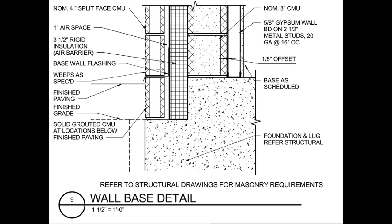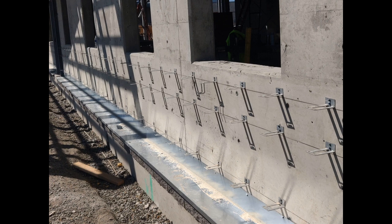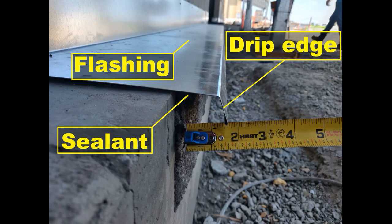Through-wall flashing and weeps. Provide reinforced membrane sheet flashing, metal or coated metal flashing. Install through-wall flashing at obstructions in the cavity and where indicated on drawings. Ensure continuity of the flashing at laps and inside and outside corners by splicing in a manner approved by the flashing manufacturer. Ensure that the top edge of the flashing is sealed by applying compatible sealant at the top edge of the through-wall flashing. Provide sealant below the drip edge of through-wall flashing.